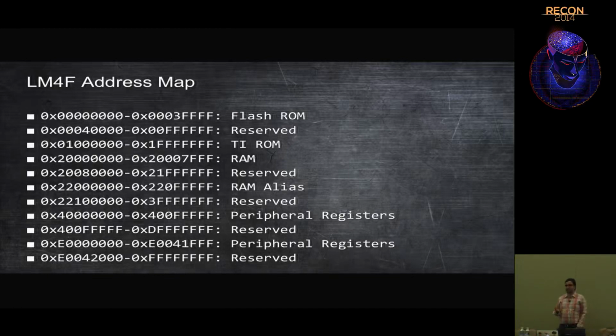And that's where you have things like the peripheral driver library that I talked about that code can use to actually access USB, to access PCI. So that's kind of like TI's operating system. They also have their own micro USB serial bootloader there. So theoretically, if you completely destroy your SMC, you can still, if you have the right hardware, connect to a serial port, to the TI ROM, and reflash the SMC from the beginning.